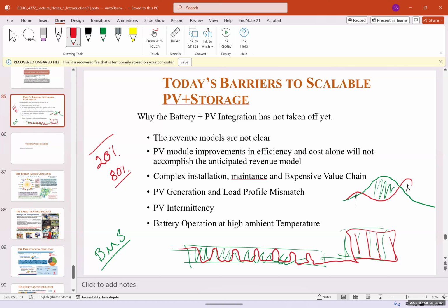But the good thing is 70% is not good for an EV, but it's still good for a grid connected system. So nowadays, when a Tesla, for example, gets towards the end of its life and the maintenance cost is too high, the most expensive part is still the battery. They take out the batteries, a few $1,000s worth of battery, and connect it to the grid and use it as a backup for the grid.